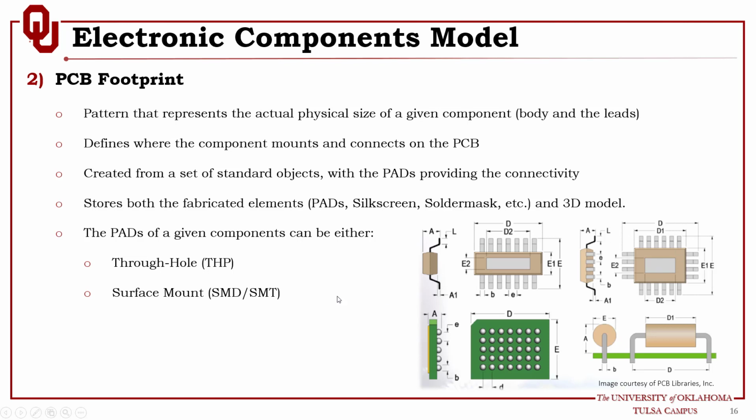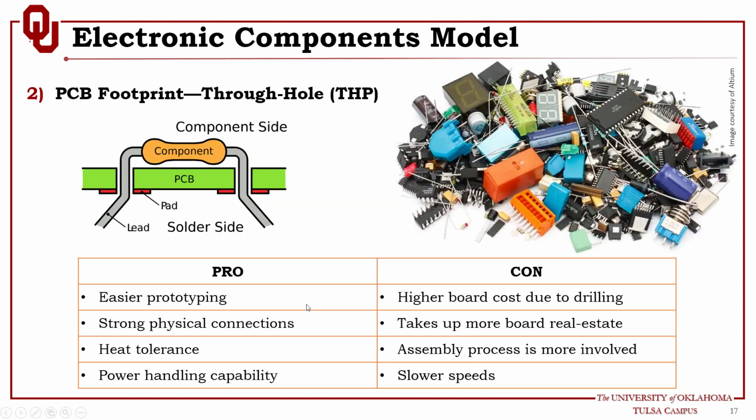Now, let's take a look at through-hole parts. Through-hole is a kind of mounting scheme used for electronic components that involves the use of leaded components. As we can see, you will have leads. For instance, this is a leaded resistor. You will have two leads in here, or if you have a diode, same thing. If you have a capacitor, same thing. Or if you have an integrated circuit, you have all these pins, for instance, in here.